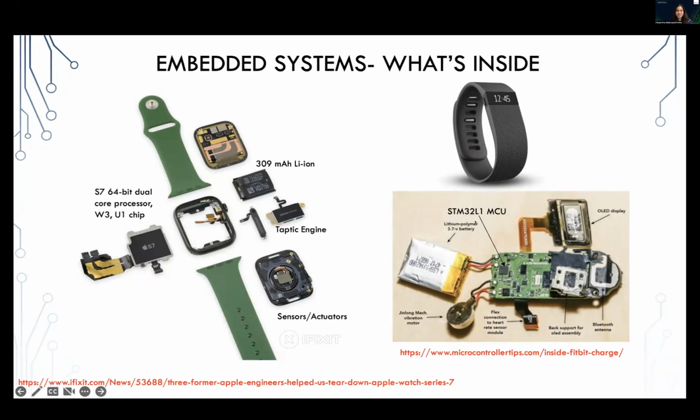So that comes to another important feature in embedded systems. Most of these systems are battery powered. That means when you are designing an embedded system, we need to be aware of the power consumption and how we manage power in the system. So using low power components is an important feature in embedded systems.